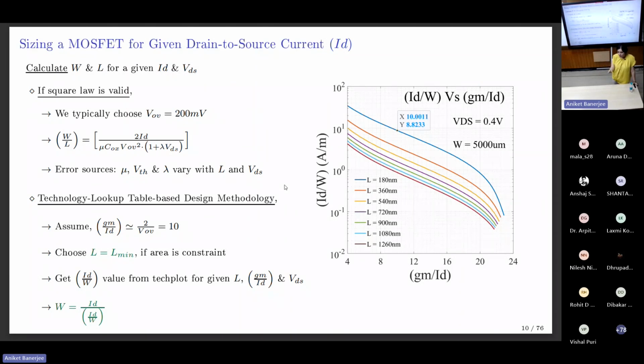So you start building intuition on gm/Id. I think it takes time, but the intuition knob just shifts in your head, and you start talking in gm/Id terms instead of overdrive voltage. Like when we talk about a circuit now, I just think, oh yeah, this is higher gm/Id, this is lower gm/Id.